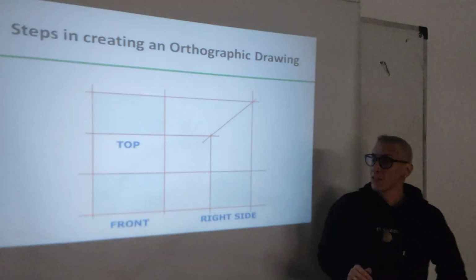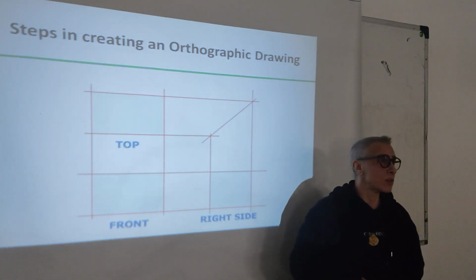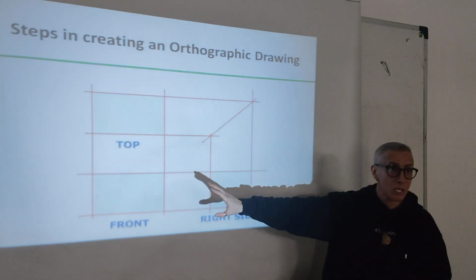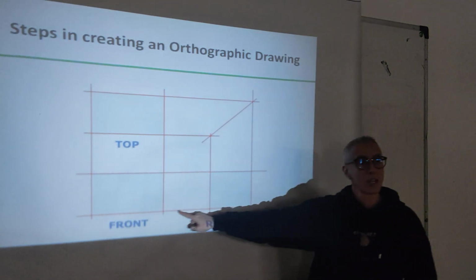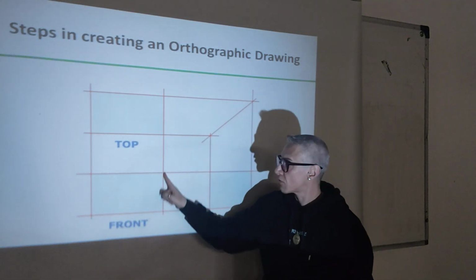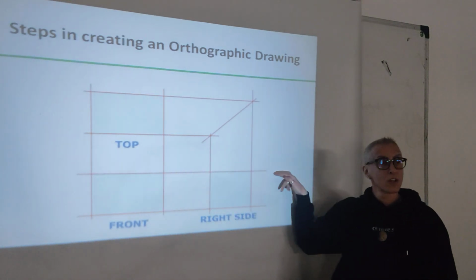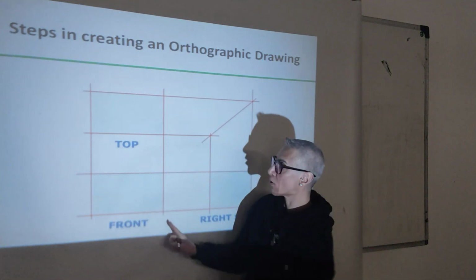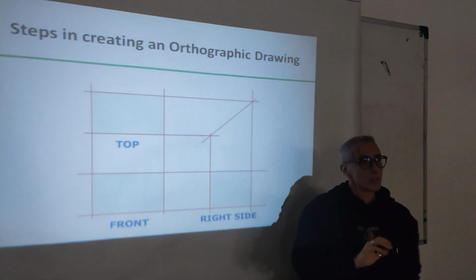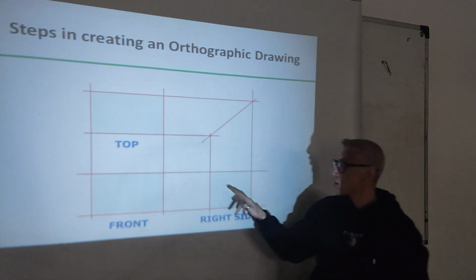In the past, when we drew the basic orthographic multi-view drawings in Introduction to 3D Design, I told you that whatever you're drawing, first you define it with a box. Maximum length, maximum height. If this is the front view, what is its maximum length and maximum height? And then you start drawing the details inside, because you need it for the construction. If I know the height and the length of this box, I can align it with the top view and leave the spaces equal. So I can organize my paper and then put inside the details: front view, top view, and right side view.